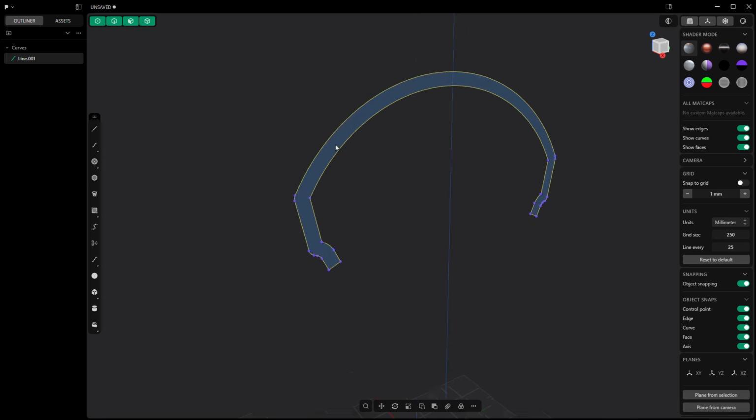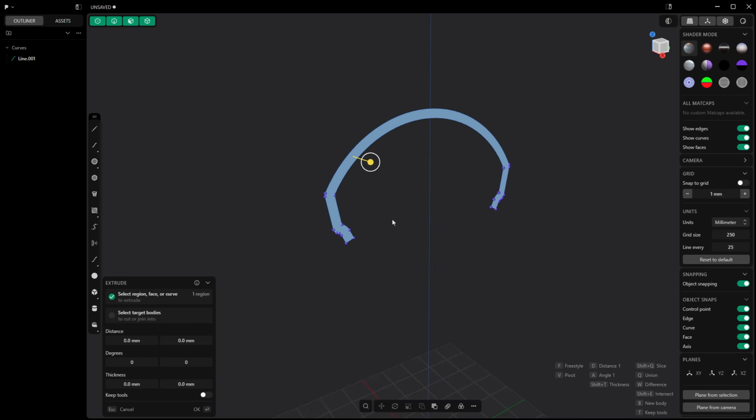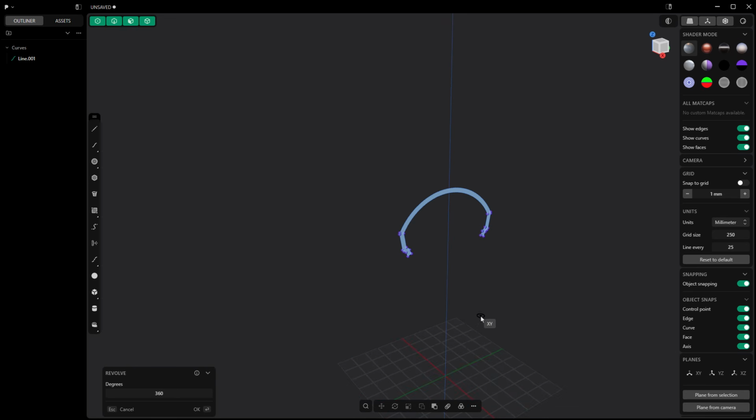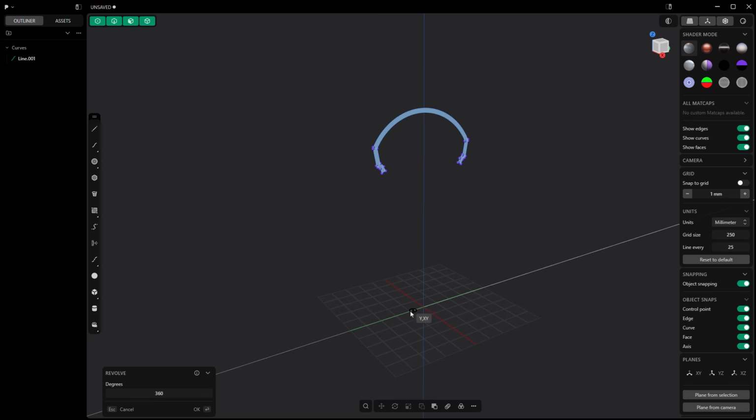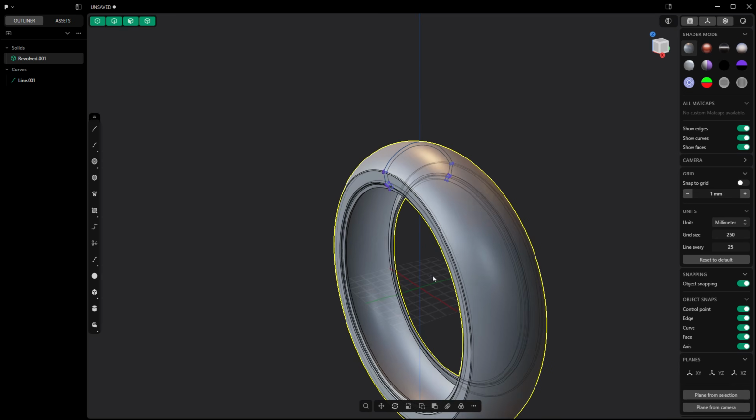The same thing is true for a revolve, and you may revolve something and it may look like a solid, but it's actually not. So you want to make sure that whenever you're trying to create a solid, you select a profile and not the curves. Once we have the profile selected, three-dot menu again, and we're going to revolve. We want to pick 2 points on the axis of revolution. So we're going to revolve about Y. I'll click on Y once, and then I'll click on Y again, and right-click to confirm.